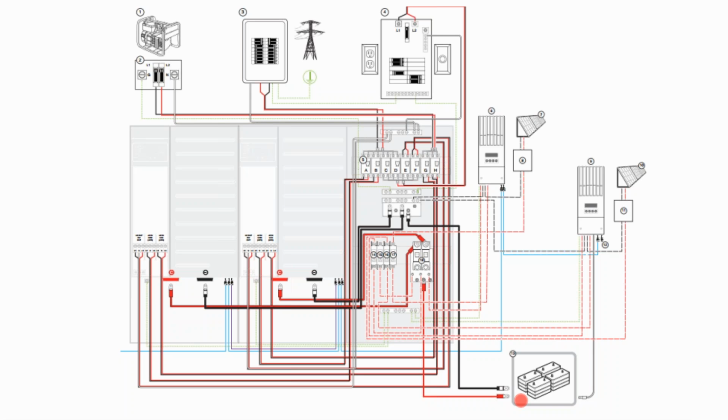Although you would have to then go in and program the lithium ion battery inverter to not discharge the batteries over greater than maybe a 25% discharge rating, so that they're not discharging in a 2-hour time frame, that you use software controls to set the maximum output. Say, hey, the forklift companies say, our batteries we're quoting you at around a 6-hour discharge cycle.